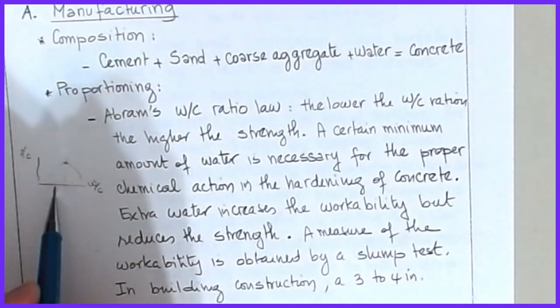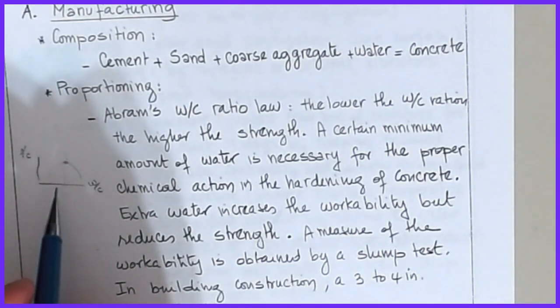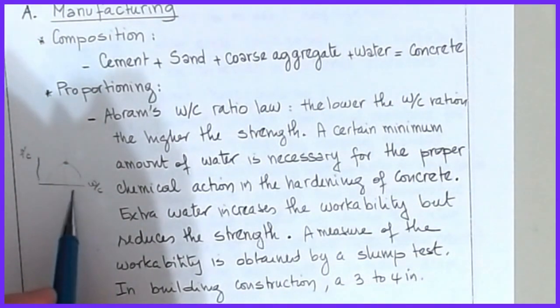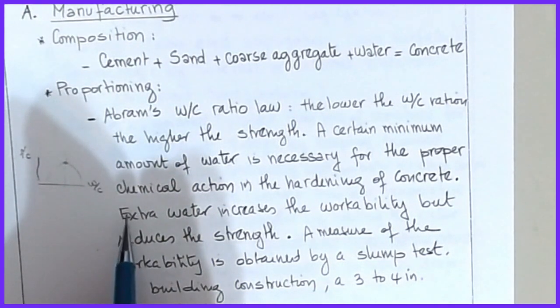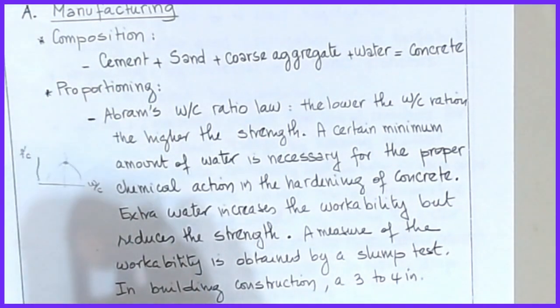And so there are some correctives. Additives known as water reducer or superplasticizer or things like that can greatly improve the workability but not affect the strength. But again, it's easy on a job site to grab a hose and just add water to increase the workability, but that's a danger that you've got to be always aware of.